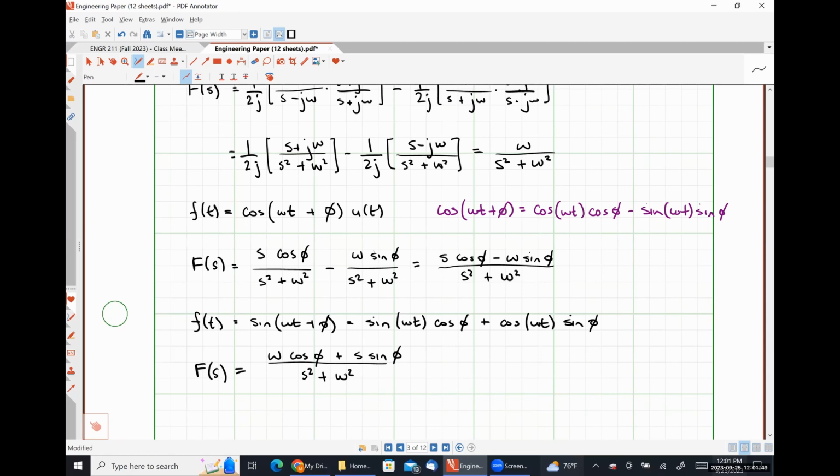Now, are you asking about just average power in general, or specifically maximum average power transfer for the homework problem? Okay, so maximum average power transfer occurs when the load impedance is the complex conjugate of the Thevenin impedance connected to the source. So for your problem, I believe you had 48 ohms plus J32 ohms. So in order for maximum power transfer to occur, the load needs to look like 48 minus J32.